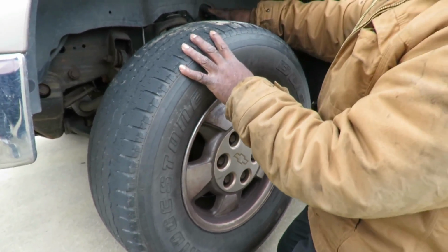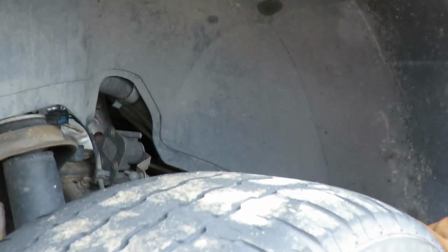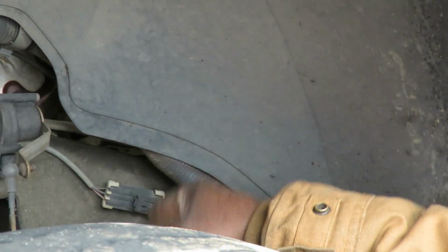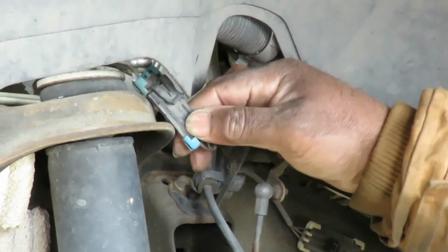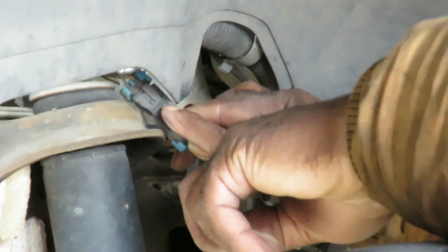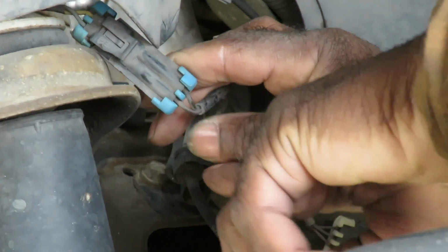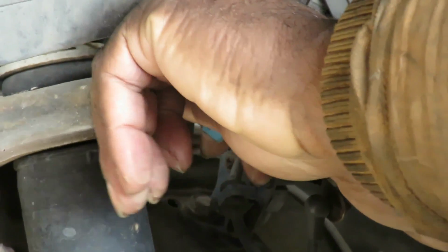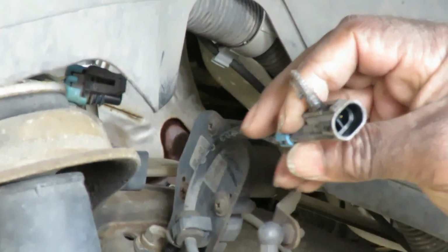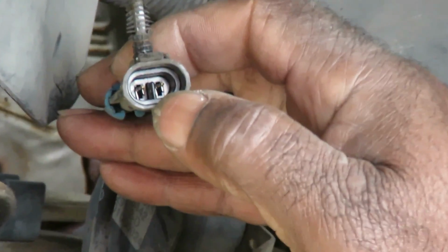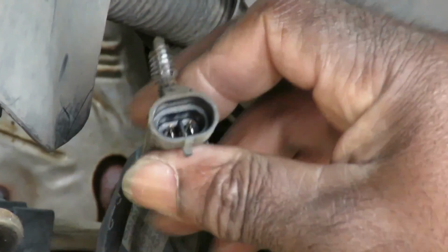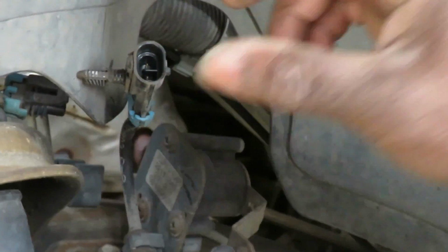All right, now if you look back here, you're gonna see some wires. You're gonna see a 3-wire connector over here. Don't touch it. Leave it alone, don't bother it. That's not the one. The one you want is right here. So go up here, pull this connector down, and then you see that little tab right there. That little tab is gonna push out a little bit and then unplug it. This is the wheel speed sensor right here. So unplug it, and there we go. Now you're going inside of this connector, you're gonna see 2 terminals inside there. All right, so what we're gonna do here, leave that alone.